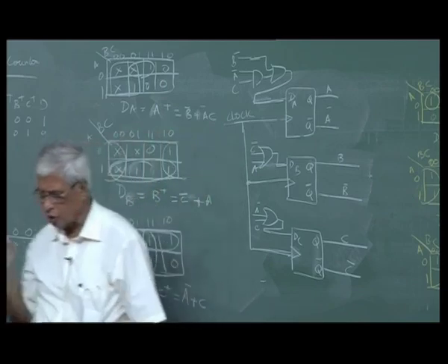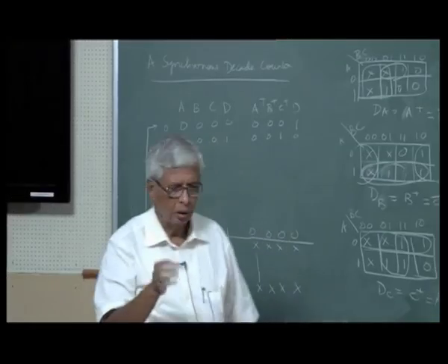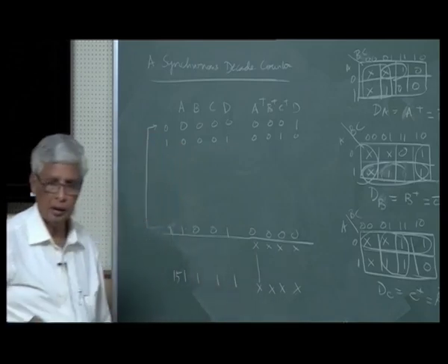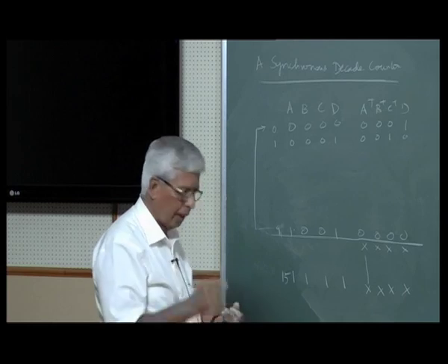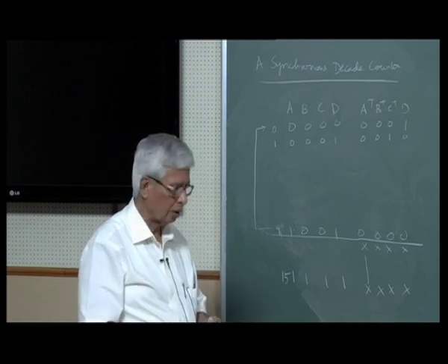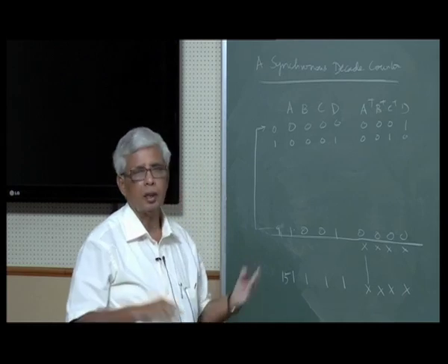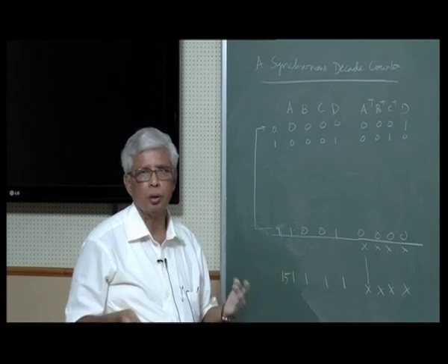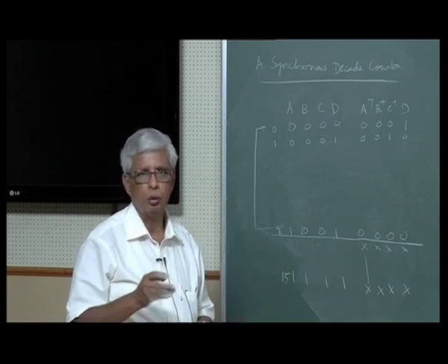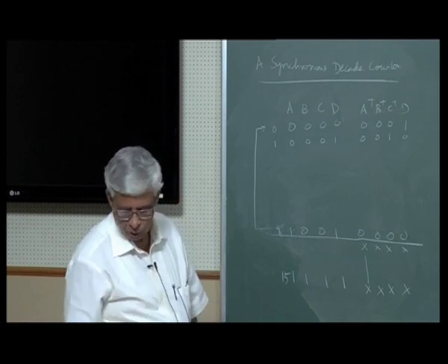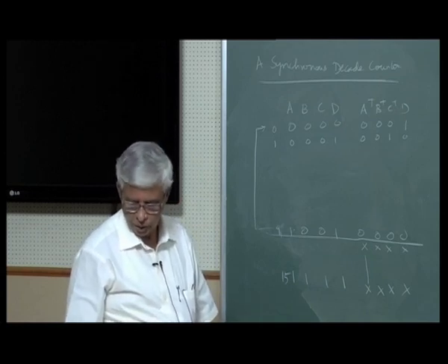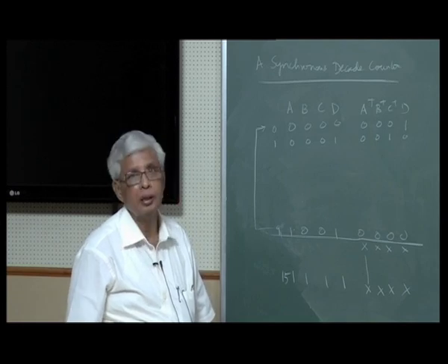So this is one shot, in one single shot. We have covered a lot of material, because we can now design an up counter, down counter, non-sequential counter, decade counter, whatever synchronous counter you want. It is so easy to do, and that is why most of the time we use synchronous counters. Ripple counters are not used very much.